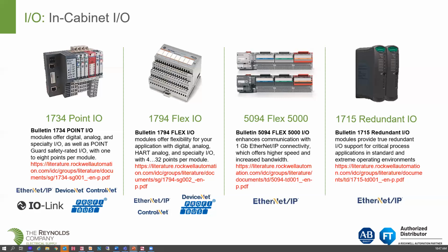And this is the first IO platform we have where we have an option not to use copper RJ45s. We actually have a comms adapter that we can use SFP, so we can take fiber directly into this remote IO. So people have been asking for this for quite a while, so that is now a viable option. We can support both a device level ring and parallel redundancy protocol out of it also. So that's another reason it's part of our process IO. Also, the HART cards are available for this, and we do support HART 7.